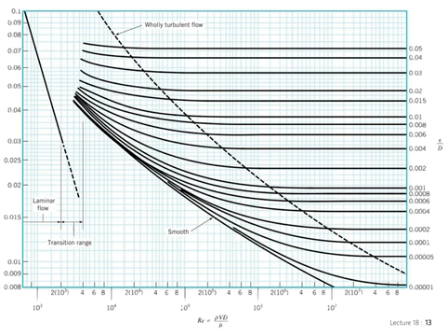So remember, we said friction factor is a function of Reynolds number. Here's the Reynolds number, and here is the surface roughness. And here on the left, you don't have anything, but that's actually F. What you read here from the left is the friction factor as a function of Reynolds number and surface roughness. So for a given pipe, a given diameter, you get your relative roughness and say it's this one.